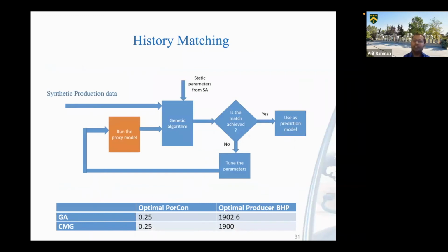Now, the history matching. The act of adjusting the developed model with real reservoir production data is called history matching. History matching is capable of improving and validating the reservoir model based on an iterative process. This approach analyzes the reservoir parameters and gets informed from the data set. Then it incorporates the reservoir characteristics with the observed data to tune and train the simulated model. After performing this process, the model will be ready to predict the production data for the studied reservoir.